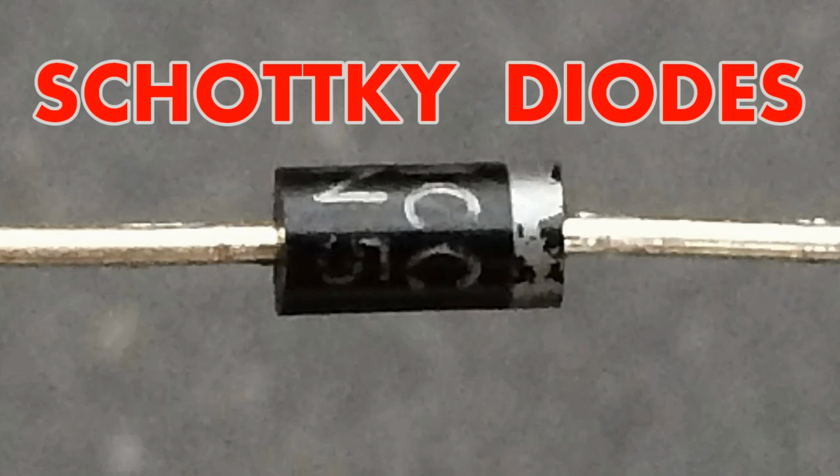Switching efficiency. Diodes with lower reverse recovery times switch from the on state to the off state more quickly. This reduces power losses and improves the overall efficiency of the electronic circuit. Fast rectification and switching. In rectifier circuits and fast switching applications, a lower reverse recovery time allows for quicker switching, enhancing circuit performance and response time.